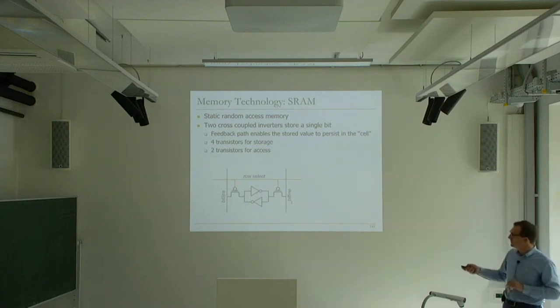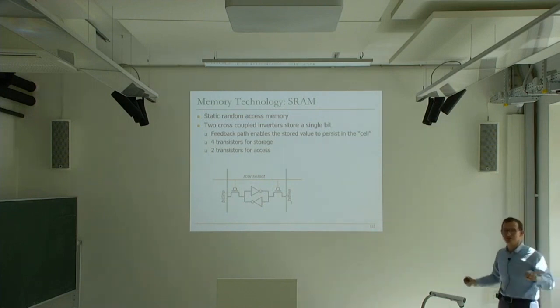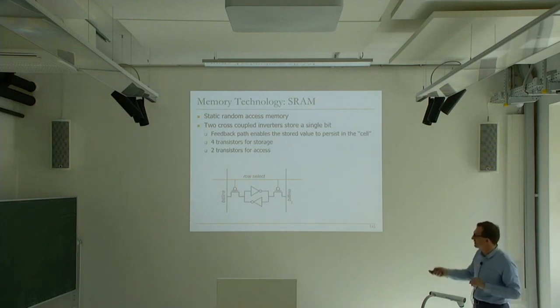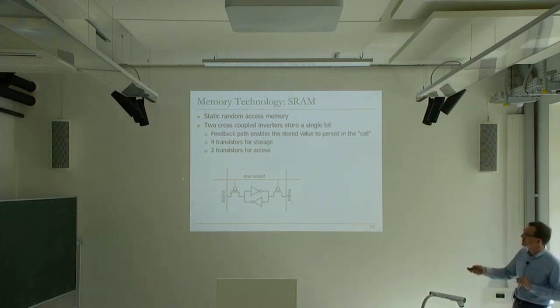What normally people do is you have 2 transistors, so you can get the value over here and the value bar over here, the complement over here. And then you can do differential sensing in the bit lines. You can sense the difference, and then you can say whether you have 1 or 0. And again, this is also a row. It's a word line, basically. So you have many of these cells that are connected to the word line.